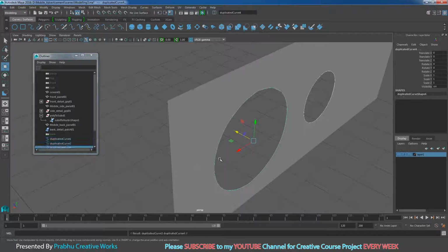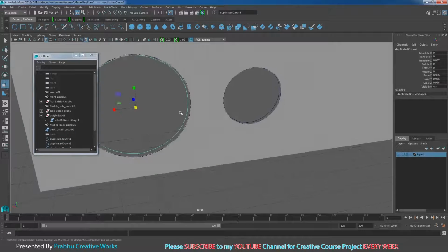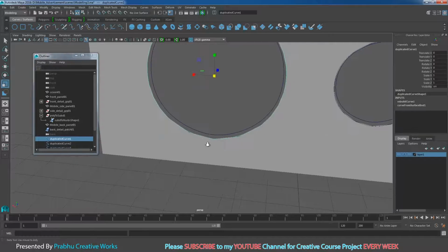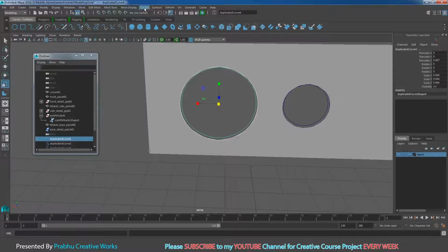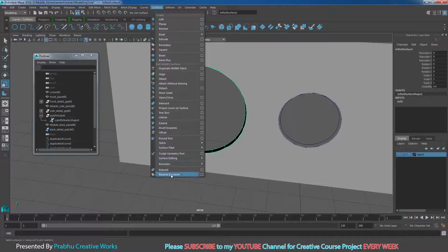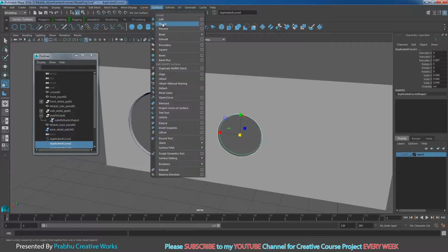Now I select both knob circles in the outliner using control. Press Ctrl D to duplicate and move a little bit inside. I will select this knob circle and press R on the keyboard, and scale it a little bit in the middle. Do the same thing on this knob circle. When this knob circle is selected, shift select this knob circle, go to surfaces and choose loft. I will select my surface over here, go to surfaces and choose reverse direction, so it will be perfect.